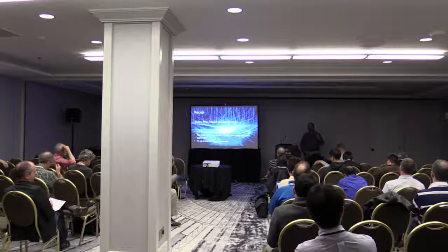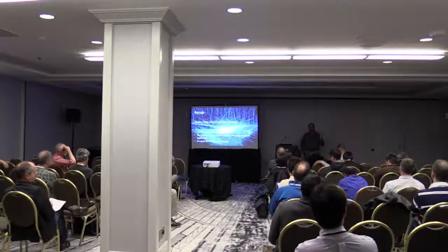So there's two things there. There's this concept of edge computing, or people talk about, like Cisco talks about fog computing. Basically what we do is we take some intelligence and we push it down to where something's actually happening. And that's where the control system lives, because it has to live there. If the cloud's down and the oil rig catches on fire, we can't interrogate the cloud to see if we should turn on the fire system. So you've got to have some control and smarts down there at the edge level.